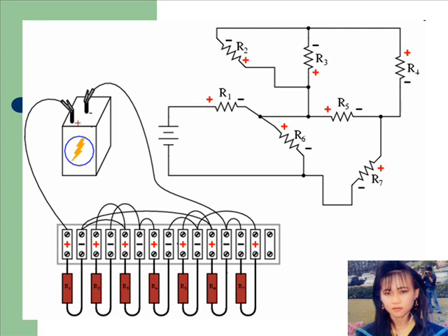However, I could have placed this wire instead between the left terminal of R2 and the right terminal of R1. Since the right terminal of R1 is already connected to the left terminal of R3, having been placed there in Step 9, it is electrically common with that one point. Doing this, though, would have resulted in 3 wires secured to the right terminal of R1 instead of 2, which violates good terminal strip etiquette.